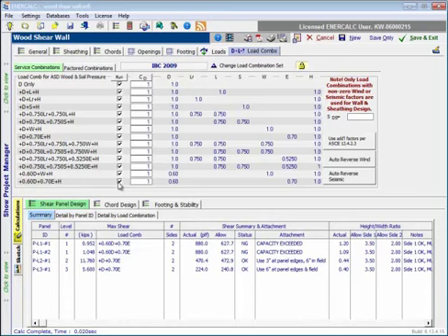Now for the sheathing, that's not much of an issue because that's pretty much all we would look at the sheathing for in a shear wall type sense anyway. However, if it happens to be an exterior wall subject to wind loads, then it's important to understand that you might need to take a look at the design of that sheathing for the out-of-plane effects.